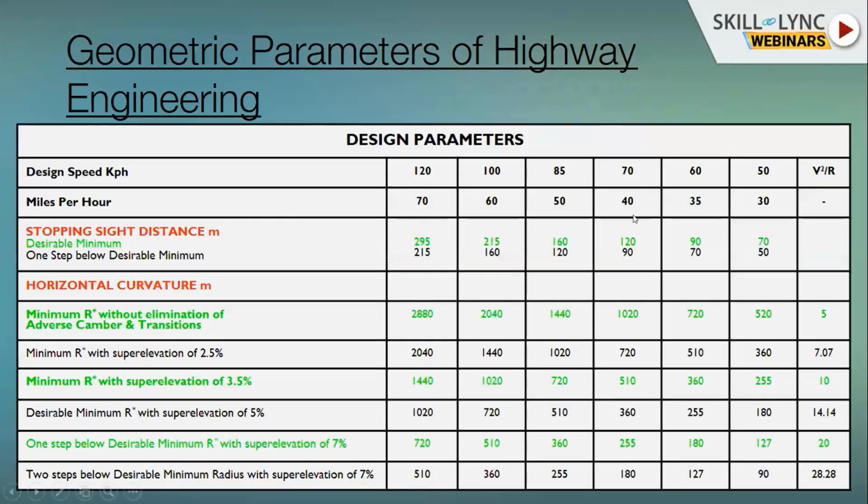So here is a table I would like to share, which is from the UK standards called DMRB, the Design Manual for Roads and Bridges. I have summarized the important parameters we use for the geometric design of horizontal as well as vertical sections. In the left hand column, you can see the particulars we are trying to achieve here, which has the design speed.